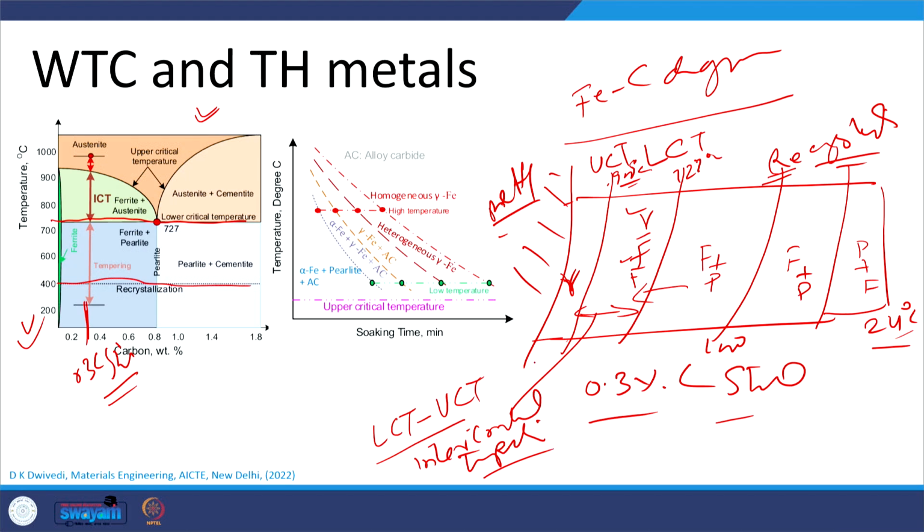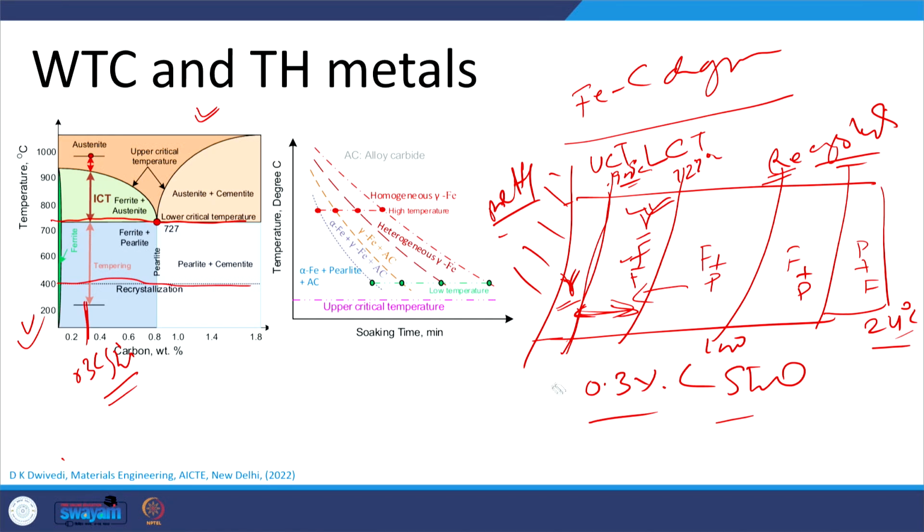So, when the metal is heated, all the zones heated during welding in the intercritical temperature range will have a mix of austenite plus ferrite, and the zones heated above the upper critical temperature will have austenite only. Okay, that is all. Now we will try to see things in a little better detail. What happens when cooling is done from these different conditions? Let me just erase it out.